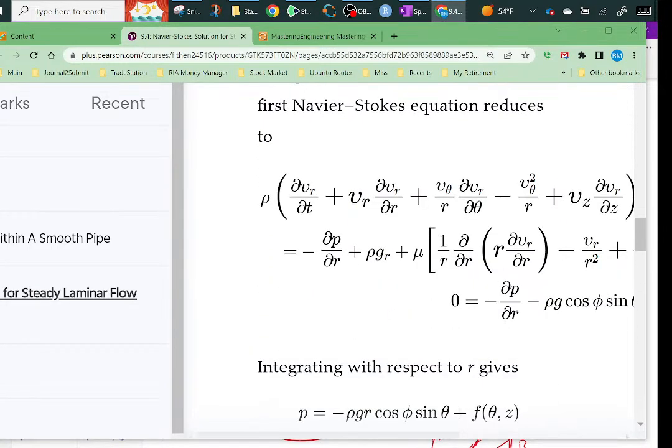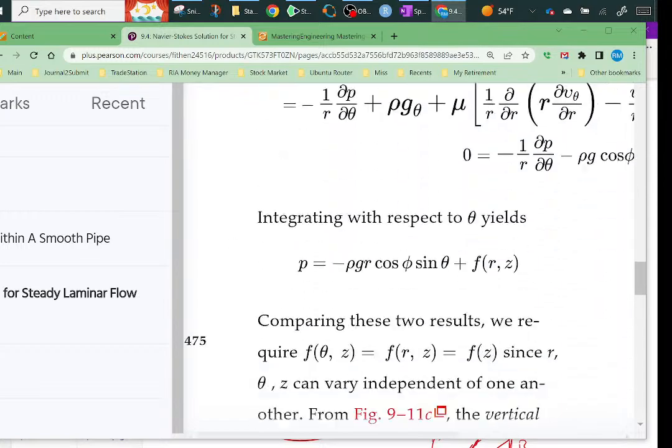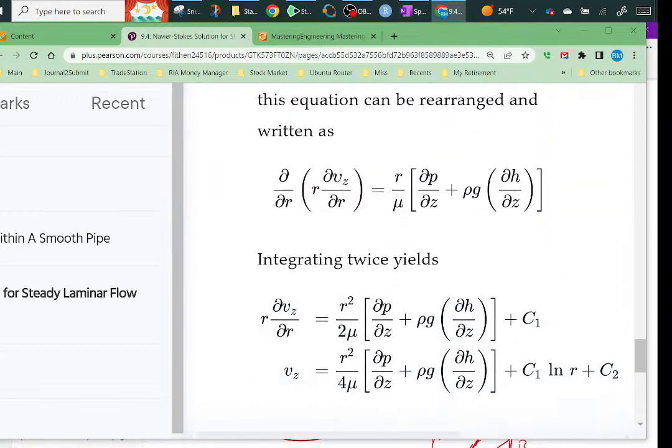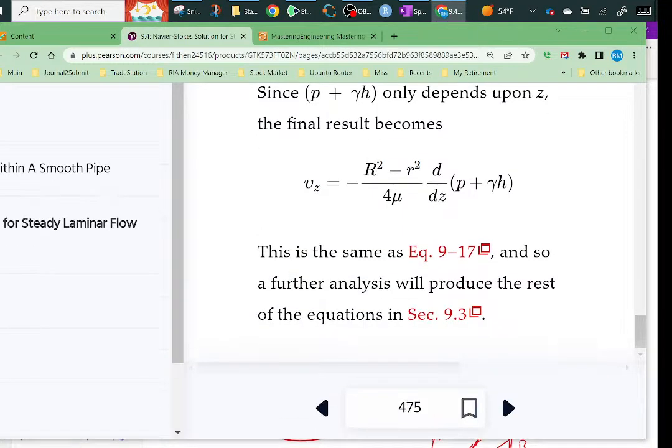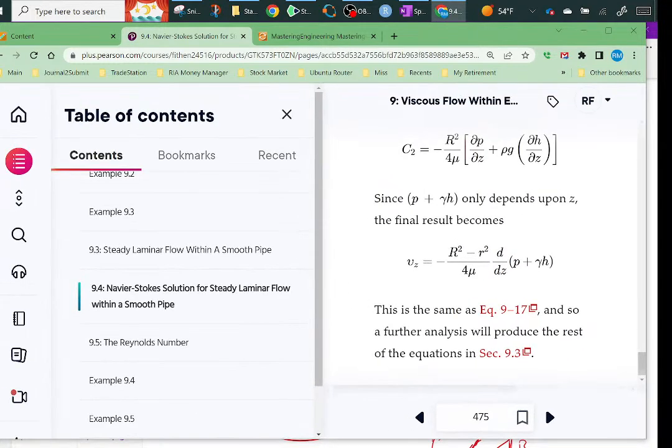Okay, now he's coming up with the whole Navier-Stokes equation. Here's what's so funny, just a side point: you've got a velocity times the derivative of the velocity. This is the nonlinear component in these parentheses. On the right-hand side, it's all linear. If you have any sort of velocity movement, you're going to get the nonlinearity, so you can't avoid it. That convection term complicates things drastically. But you can ignore it, which is what he's done here, because for laminar flow you can ignore that.